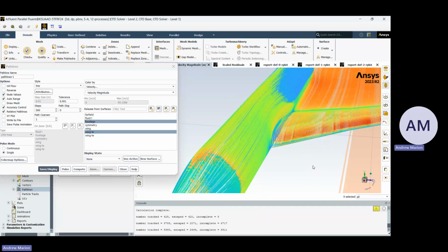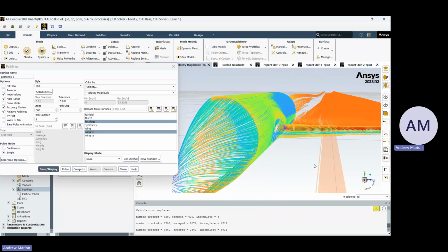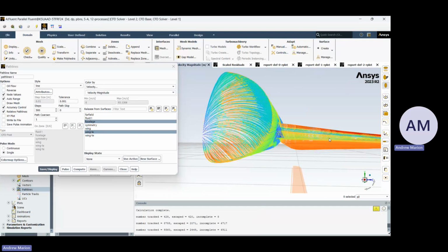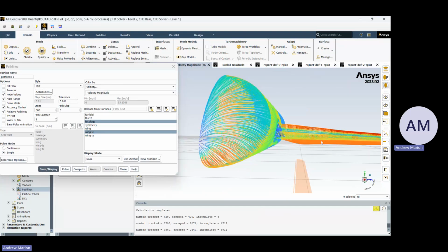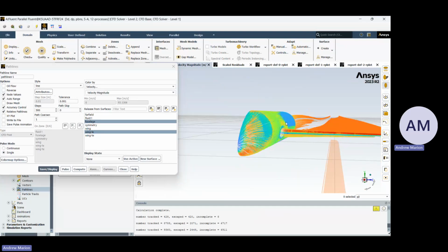Because there's two types of drag. There's parasite drag, which happens at zero angle of attack. That comes from surface friction, and the pressure differential from the high pressure where it hits the nose, and then interference drag. And then there's induced drag, which is drag that's from lift. Because you get that pressure differential, but it's also acting in the X direction if you had an angle of attack. So lift also adds drag when you produce it, and that's just an undeniable fact that you can't get around.